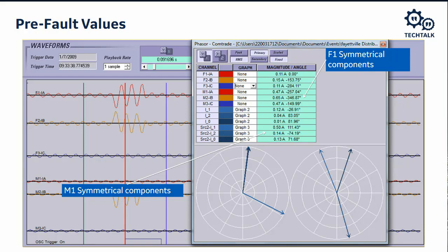Now, what that means is that it would be next to impossible to completely balance a distribution system like this, because you can never predict when someone's heat pump is going to kick on. If I'm on A phase and my heat pump kicks on, it's going to pull a little bit more power than when my neighbor may be on that B phase and the other neighbor may be on C phase. But because of the diversity of the loads, it's going to be next to impossible to completely balance a distribution system like that.